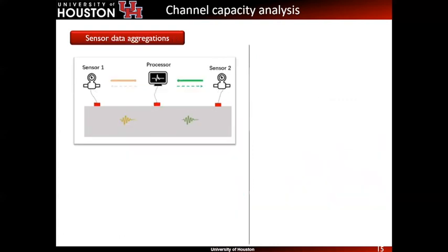In another application, we consider the multiple sensor data acquisition problem. In this scenario, a cluster head wants to collect and process the data from nine pipe sensors. SC-FDMA means single carrier frequency division multiple access. It has a low peak to average power ratio and is more attractive than OFDMA in the uplink. The goal is to maximize the rate sum capacity of the SC-FDMA.